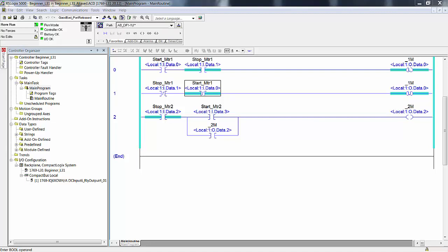Nonetheless, in most cases out there, you're going to be given a functional specification, or you're going to have to interview the mechanical designer, the machine builder, or the customer, and you're going to have to write up a functional specification based on what they tell you and what you see, and then you're going to hand that to the customer. They're going to read it and say, yes, that's it, or they're going to say, no, that's not it, and here's why. And you will keep massaging that document until the functional specification is what both you and the customer agree on. This is what you're developing the control system for, and you're going to program it to do these things.